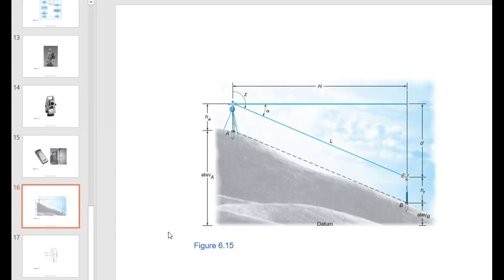You always want to make sure you're actually shooting the prism and not something that got in the way, or missing the prism and getting some other type of a reading from some random object.